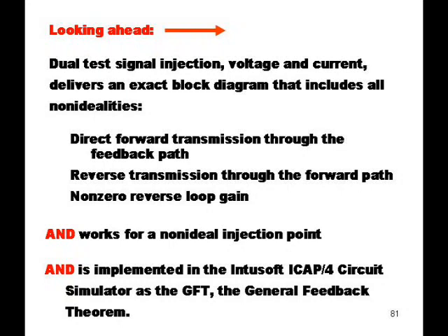And this is trouble because just the place that we want to know the accurate answers is in the neighborhood of loop gain crossover, because that's what determines how the closed loop response drops off. It determines whether there's significant peaking and ultimately determines whether it even goes unstable. So the neighborhood of crossover is just where we want to get accurate results, and that's where these normal assumptions of unidirectional flow in the two boxes breaks down. So that's where it's important to know what a better model is.